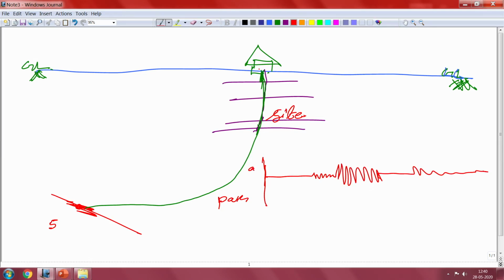Like this you are seeing this. So, this will be the acceleration or velocity and this will be the time. We have noticed that the durations are defined as a function of your acceleration values or the square of acceleration. Acceleration means you can take 0.3 g or 0.05 g where it crosses. Or you can take the Husid plot where you will integrate acceleration squared and it gives 5% to 95% energy, or sometimes the uniform duration aspect where 0.1 g or 0.01 g is taken into account.